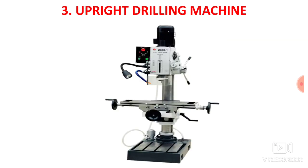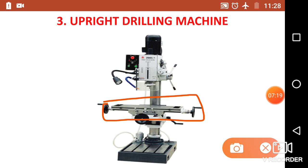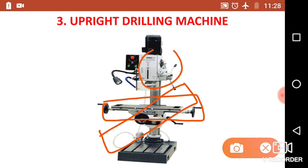So here you can see the diagram of the upright drilling machine. This is the table of the drilling machine. This table you can attach at any angle. You can rotate this table and you can fix this table. Again you can rotate this arm also. So you can drill the hole at any angle with the upright drilling machine.